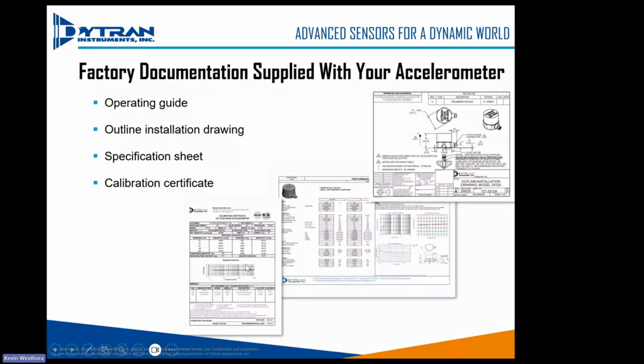There are two things I wanted to highlight here. One, the reference sensitivity of an accelerometer is the 100 hertz data point of the accelerometer. So that's what you would see on your calibration sticker. That's what you would use to enter into your data acquisition system as you set it up. And then the other piece of information I wanted to highlight is that we have the capability of going down to 1 hertz and the ability to go up to 17 kilohertz. But we're accredited through ISO from 1 hertz to 10 kilohertz. Okay.